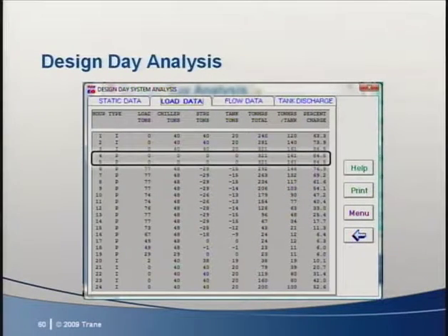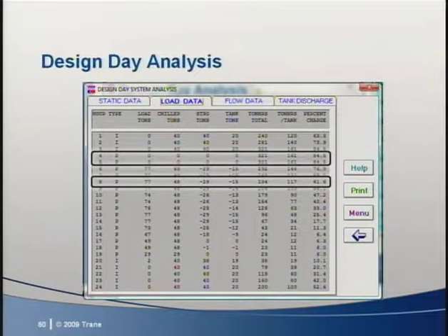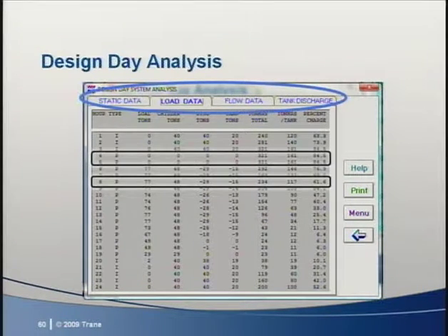Let's look at some. Notice hours 4 and 5 show the chiller is unscheduled as there is no load and it's not charging. That provides scheduling flexibility. Notice hour 8 shows a peak load of 77 tons with the load split. The chiller provides 48 tons and 29 tons coming from the 2 ice tanks. This is about a 60-40 chiller-ice split, which is common. IcePick also provides a variety of other design information, such as pressure drops, inventory, and charging temperatures. As you can see, there are options to consider.